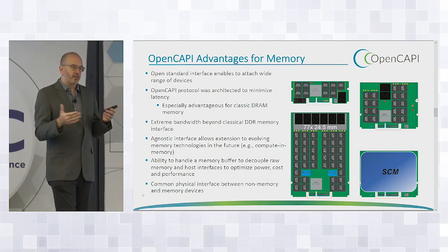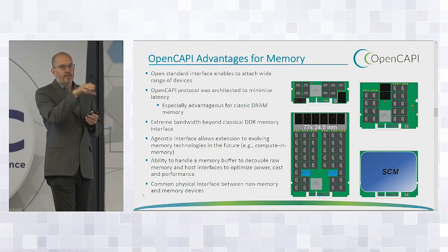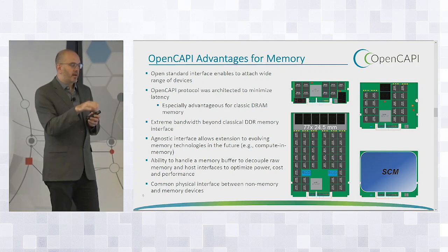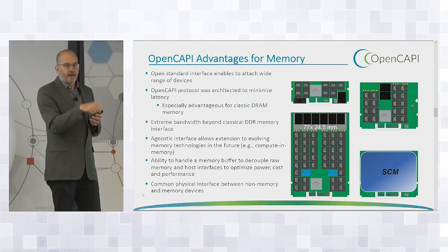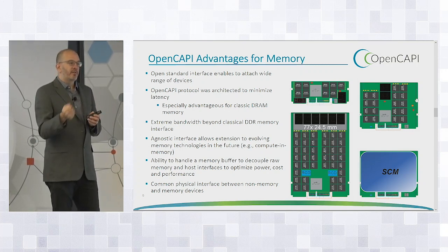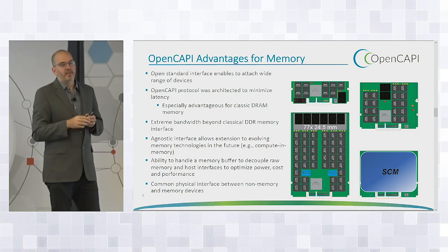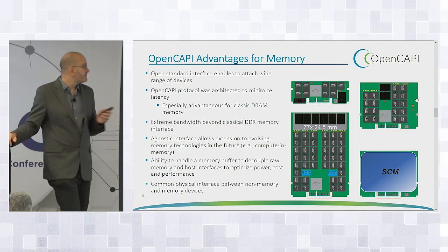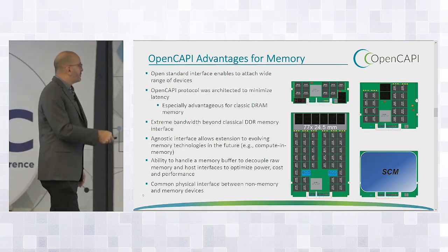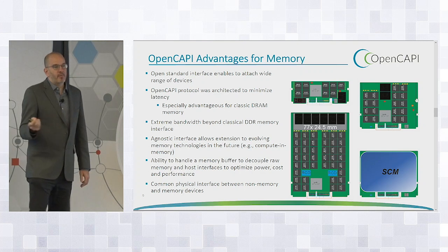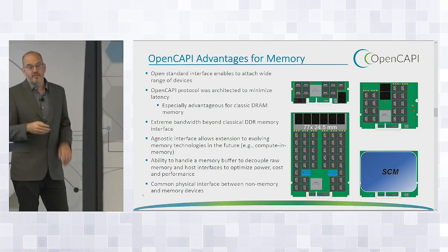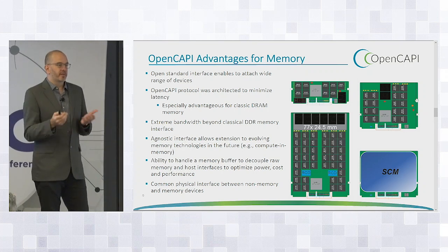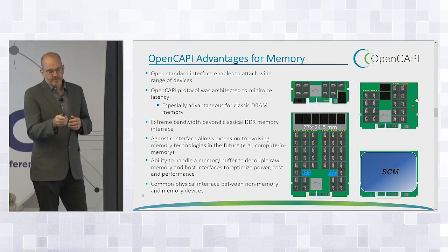We don't have switching capability in OpenCAPI. I can plug a DDR memory in with minimal latency add in the idle case. So 5 nanoseconds in the idle case turns into a positive latency in the loaded case, because I'm able to put that much more memory behind my processor. This is pretty important with what we're doing here and a big step in differentiating future IBM systems. We'd really like to get the rest of the ecosystem to pick up on this device because it really is a way to build better memory subsystems.